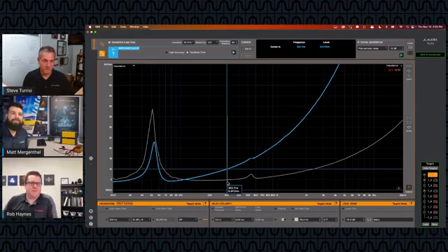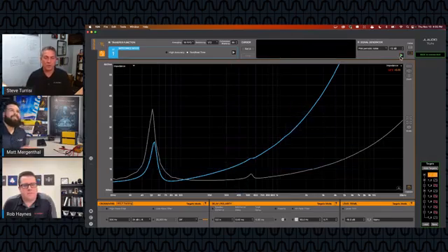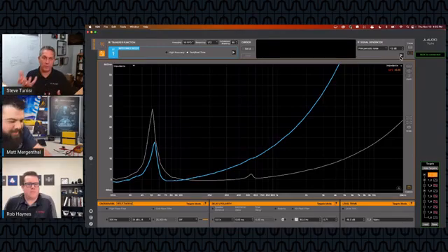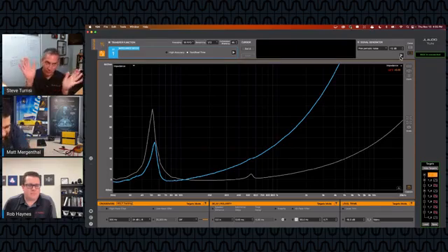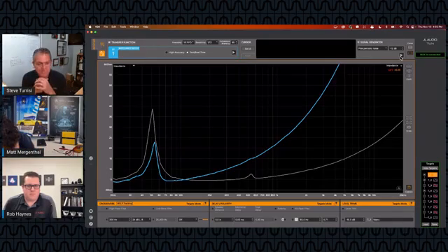Yes. And in some of our earlier Evolution product, we actually took advantage of the inductance of the voice coil to eliminate some componentry from the passive crossover network. And we took advantage of that rise as part of the speaker design. Just a little tidbit for you. All right. I'm moving on to another speaker here.